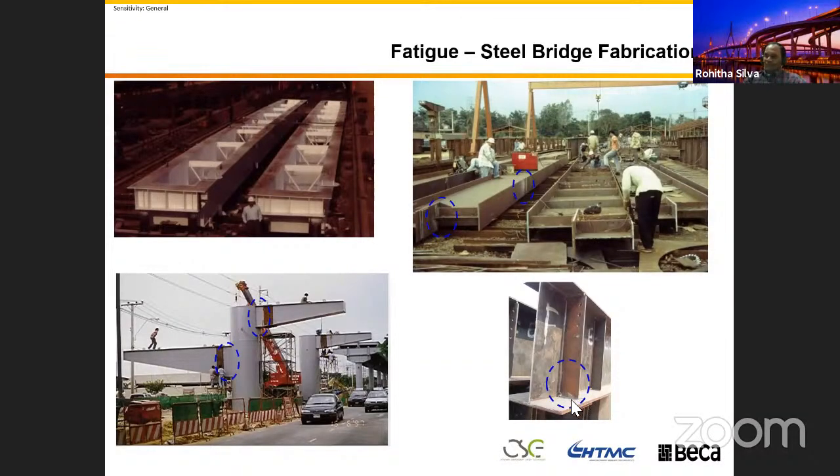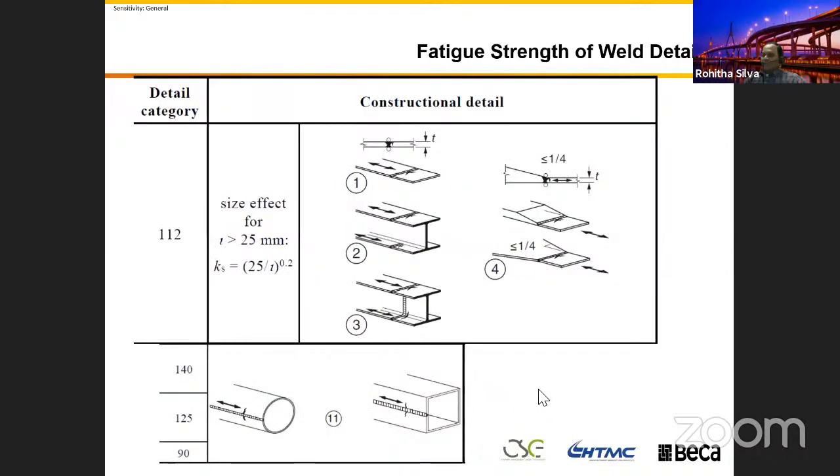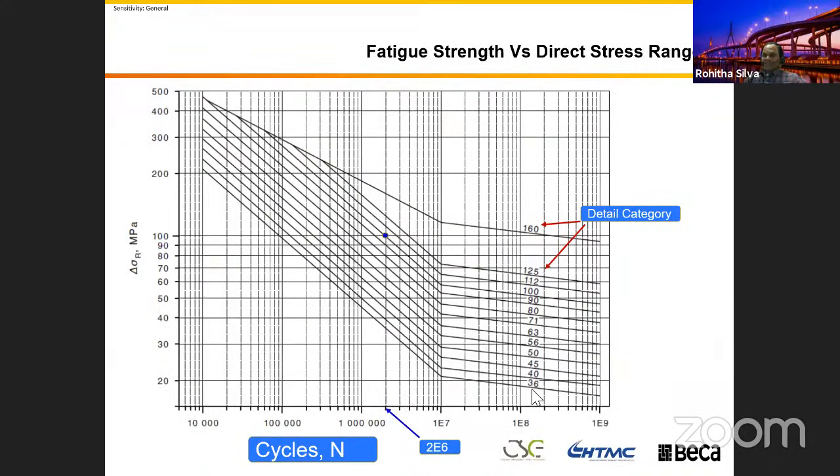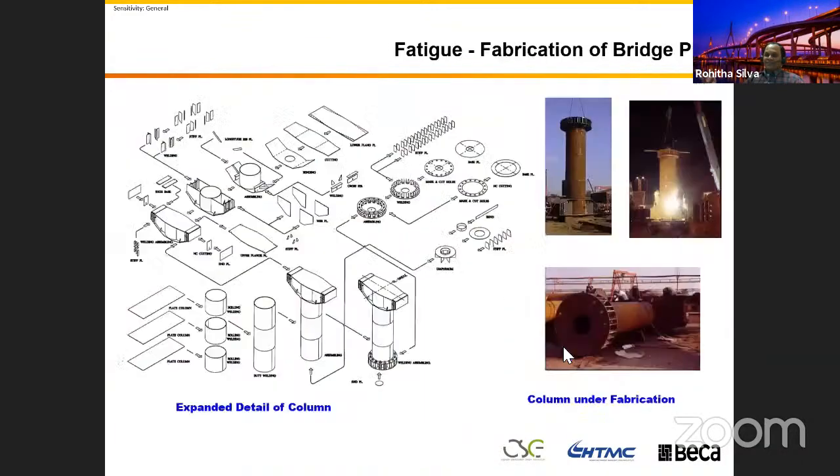Yeah, one of the lowest fatigue limits, but if you go to the Australian standard, they go as low as 36 MPa. It's about 10% of the structural steel member yield strength, about 10%. I can explain this fatigue design for so many hours, but I just want you to understand the simple point: if I summarize, fatigue failure is catastrophic. So you have to design for fatigue.